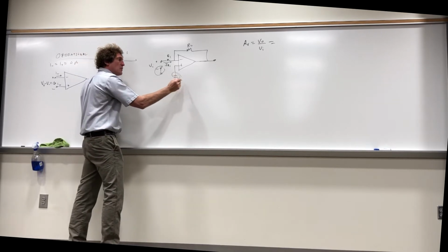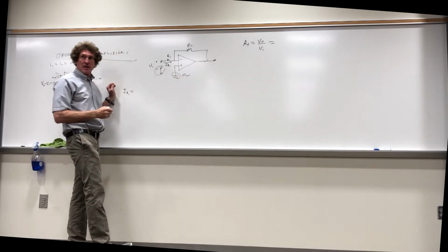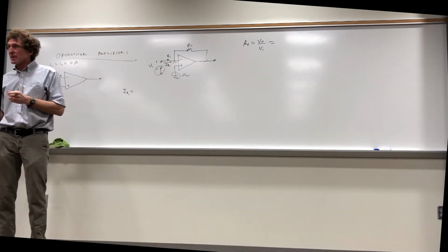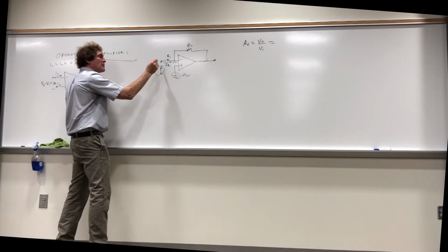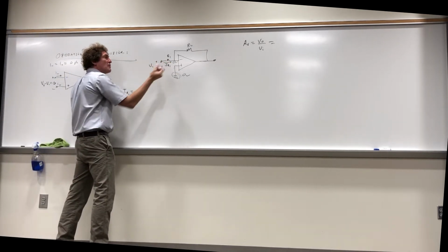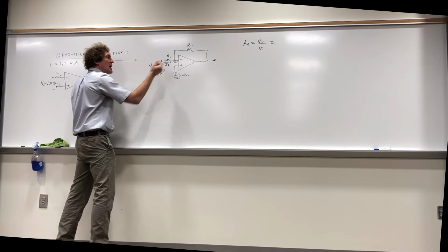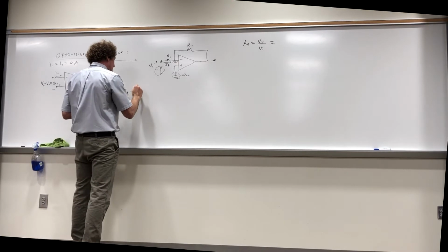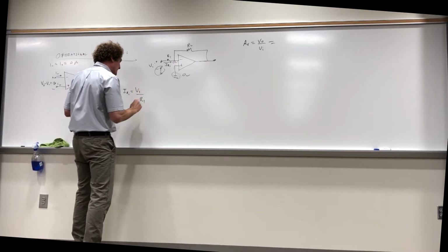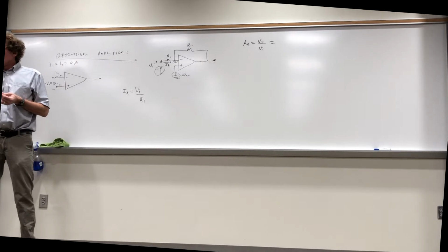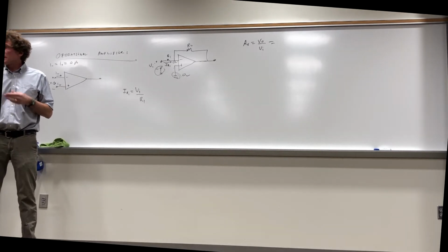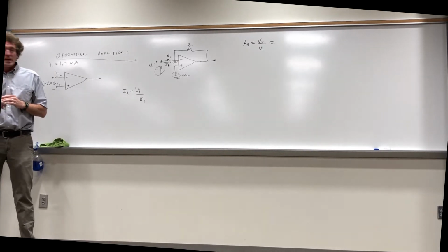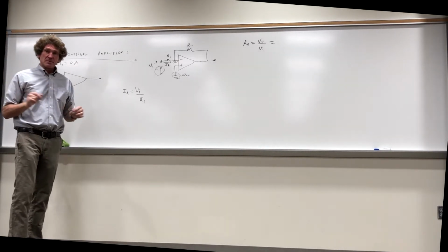We look here and we know the voltage here is 0 volts, right? Therefore, the voltage here must be 0 volts as well. Correct, class? And therefore, the current flowing from positive to that 0 volt or negative terminal would be simply Vin minus 0 over R1. So this is simply Vin over R1. That should be obvious. Everybody got that? And this is the way you would do any other operational amplifier problem that you didn't already know how to do. Now, after that, these are ideal op-amps.